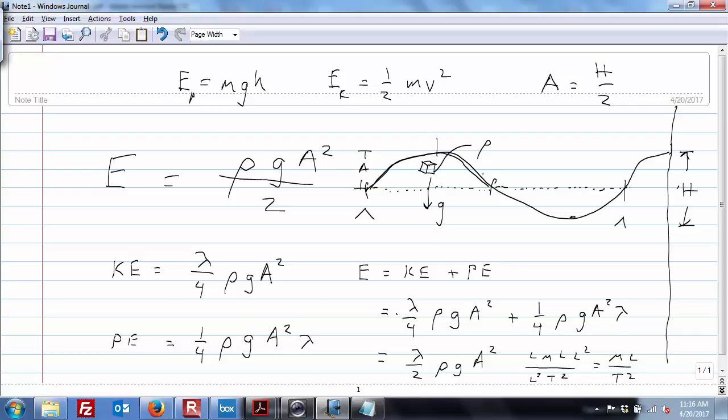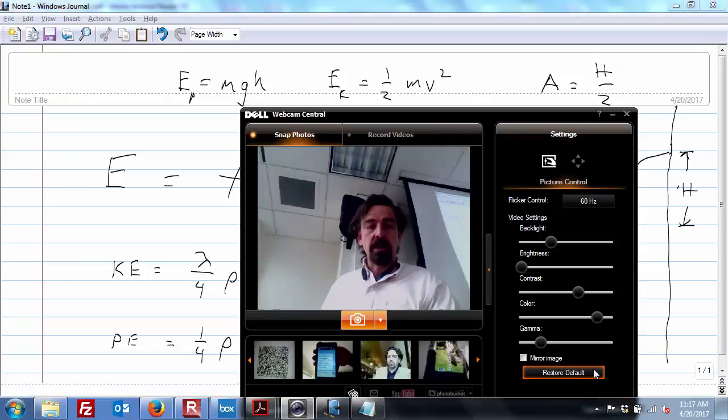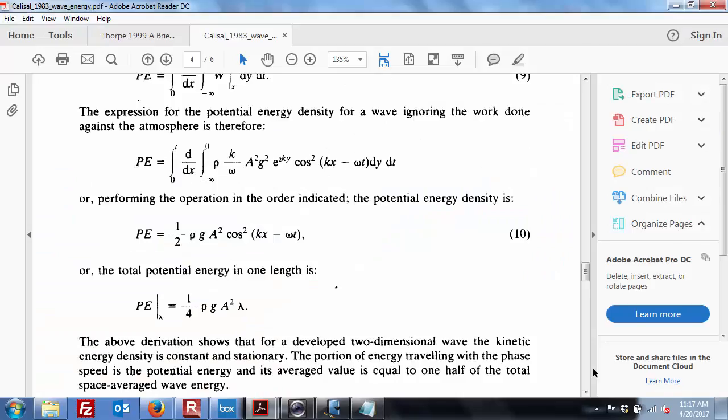Sorry that got a little bit small, but those are not the conventional dimensions for energy, so it's basically energy per length. In SI units it's energy per meter, but we're in wave land here, so it's energy per wave, however long the wave is. That's what that means. And that's why when we look at this paper, you can see it's potential energy per lambda, per wavelength. So that's why the units are a little funky. Okay. For this problem, though, we want to get to power. So right now we've just got this weird energy form.